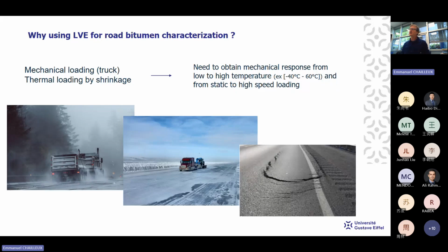But also to obtain the mechanical response for static loading, which creates mainly rutting, as you can see on the right, and also the mechanical response after high-speed loading. You know that generally the modulus increases with the speed of loading, or with the frequency in oscillation.